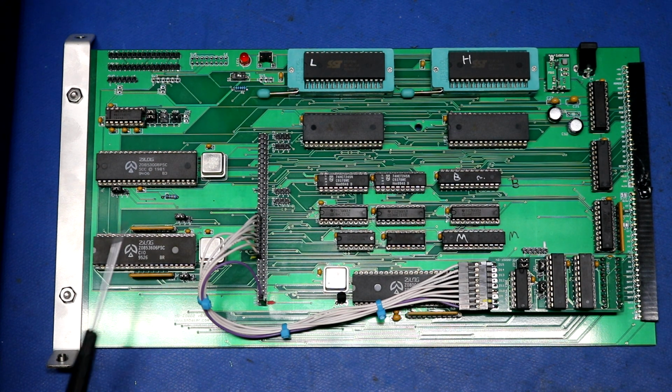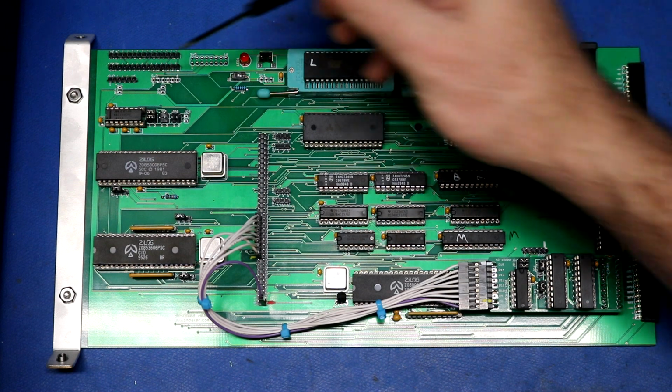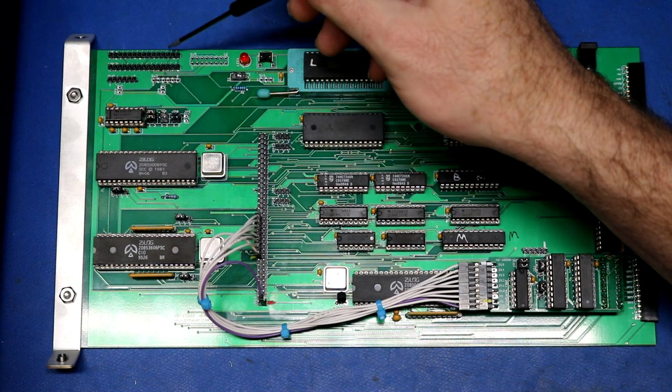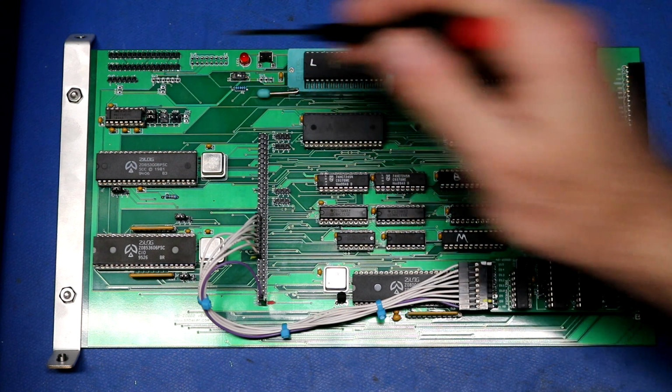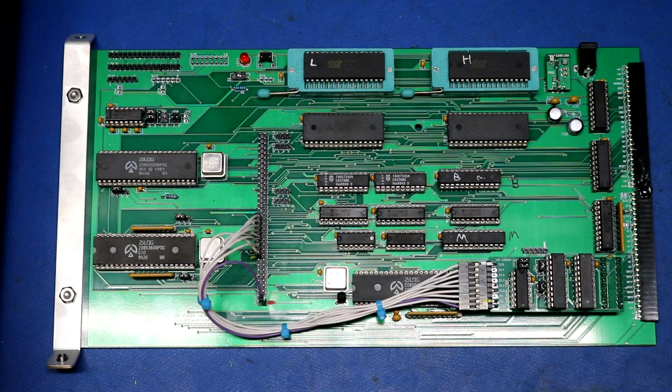So over here we have the parallel port chip, the CIO, and then we have the serial chip, the SCC. We've got a couple connectors over here that match the H8 pinout for the serial connectors. Your RS-232 transceiver, a little regulator here to give us 5 volts on the board, and the connectors going to the H8 backplane. Now this is actually a complete standalone single board computer, so it actually has a power jack here if I wanted to, and during development I did do this. I could just plug in 5 volts here, plug in a serial there, and you've got a workable computer.